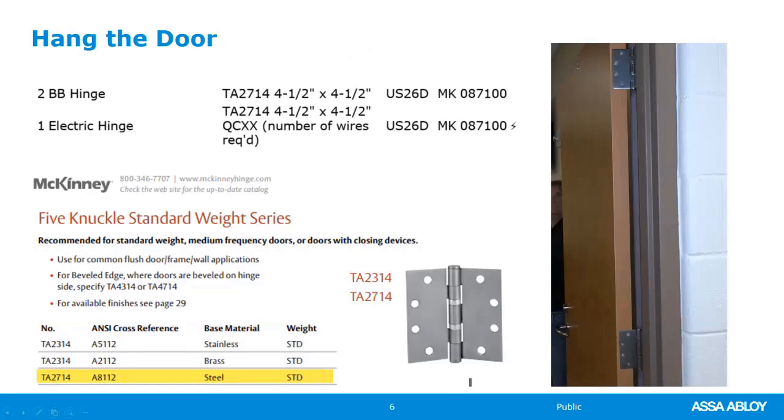And the through wire hinge will go at the center location. A top hinge usually takes the most amount of the brunt of the force when the door opens and closes. Gravity wants to pull on the screws on that top hinge. So we don't want to put the through wire hinge up in this location. We put it in the center for 2 reasons. Number 1, it's not a load bearing hinge. And number 2, it's closer as a direct shot.